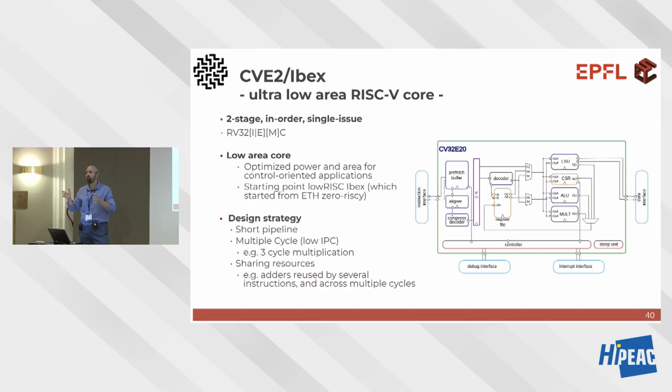So for example, if you design a system, you should specify at least the first instruction, because you need the state to be in a specific state, right? Is it going to be aligned or not aligned? And of course, the usual answer is, I'm assuming the first instruction is word aligned. It's not that you fetch the first instruction and say this is the second part of a previous instruction. It could be compressed, but should be word aligned. It's not mandatory though.